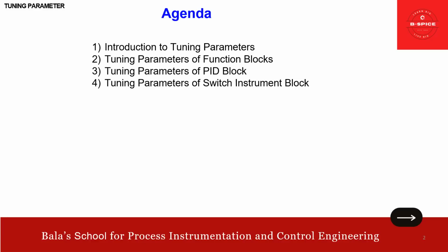The switch instrument block is used to start, stop, monitor, and manipulate the status of various types of instruments. Then tuning parameters of the motor control block. Basically, this is the block applied to operate motor-driven pumps and motor-operated valves. So these are the things we are going to cover. Of course, this is not a full list. I selected a few important items, and we can see the other items in subsequent videos.